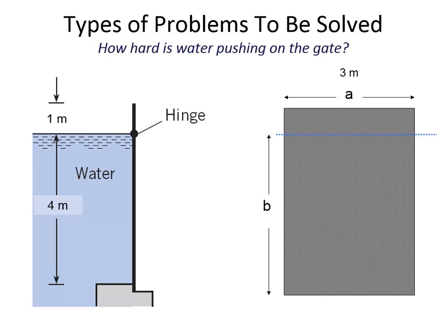only the shape that's underneath the water line. The fact that the plate continues above the water line is irrelevant to us. All that we'd need to be concerned with would be the submerged height of the shape. And remember, B is the parameter that we give to the vertical height of the plate, and it has some width A.